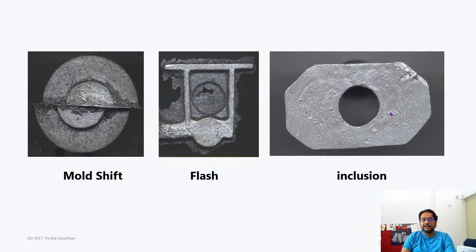So because of that, you got this kind of a mold shift error. And finally, you didn't clean up the molten metal properly, or the sand itself had some impurities which were not compatible with the casted material. So those things get included into the casting, and these are called inclusions. Sometimes it's okay to have them, you can machine it out, but sometimes they are a problem, right? What you can see on the top is like a scab that is created. This is a scab.